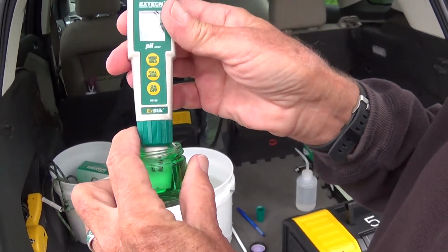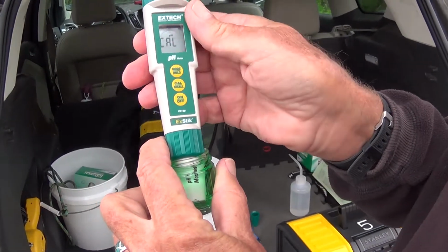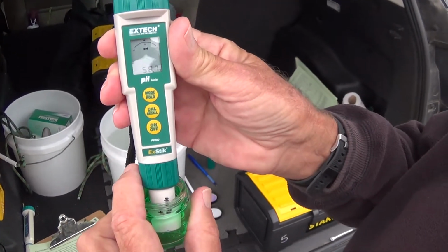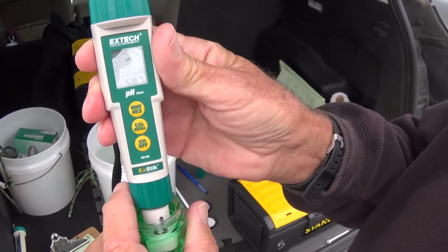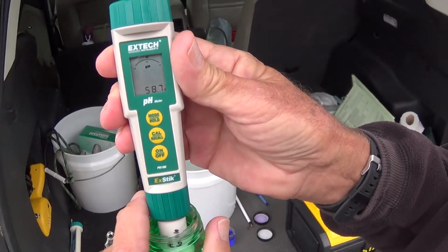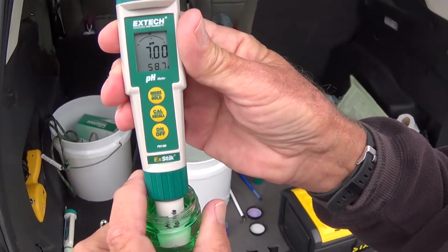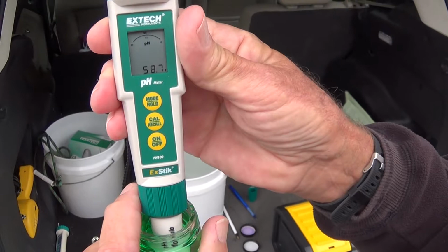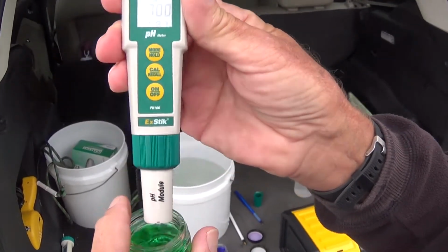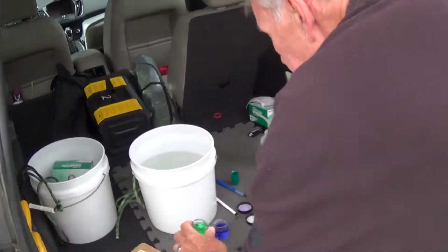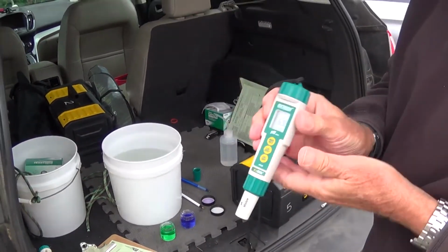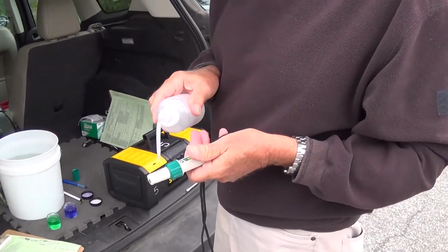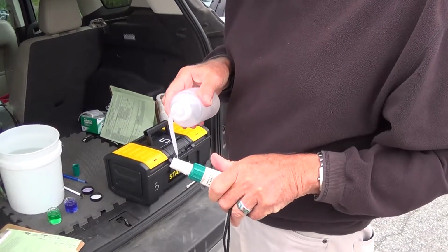So first in the solution, then it says cal. And you've got to be a little patient here. And you see the 7, it's stabilizing or calibrating to the 7 solution. And pretty soon, hopefully, it goes to end. All right. We take it out. And it's important at this point to rinse it again, because you want to get all of that 7 solution off the electrode,